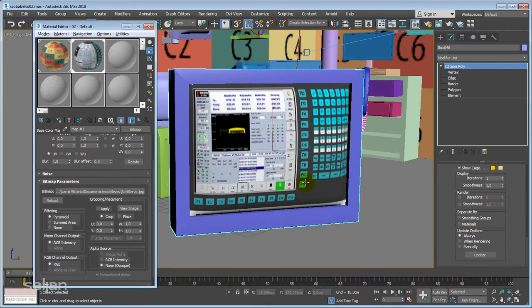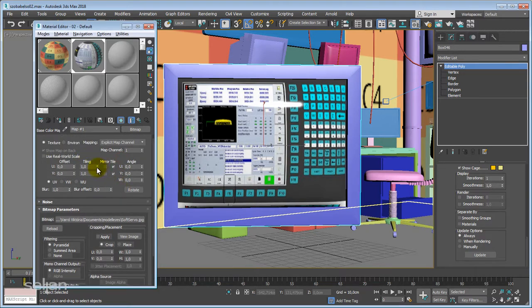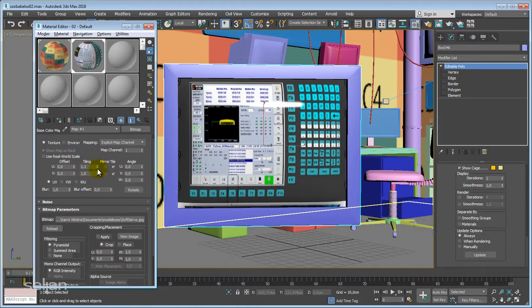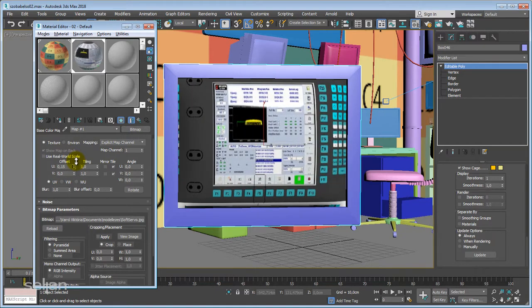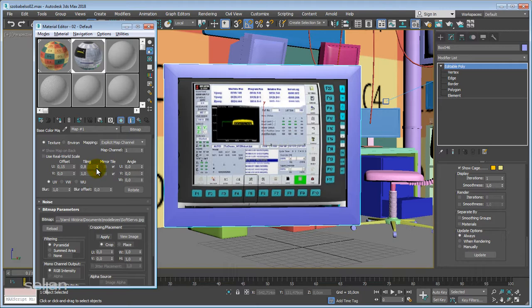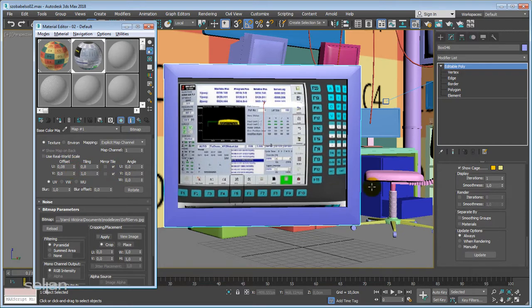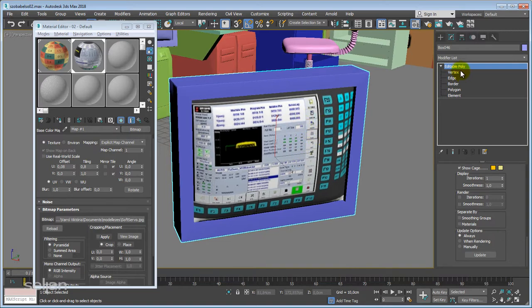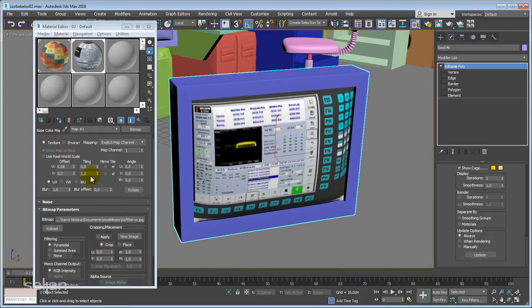Where do we go? Yeah, that's right. If you want to align it, if you want to change it, you can do the alignment and changes in the tiling or in the offset. I will use a tiling, kind of change it here. Offset. Okay, why not make an offset? Yeah, and tricking with the tiling and offset. Oh, that's fine. Okay, so I don't want to use another UV map, but actually I can do that just by selecting the polygons, these polygons, and calling a UVW map. That's it, but tiling and offset is enough for our adjustments.